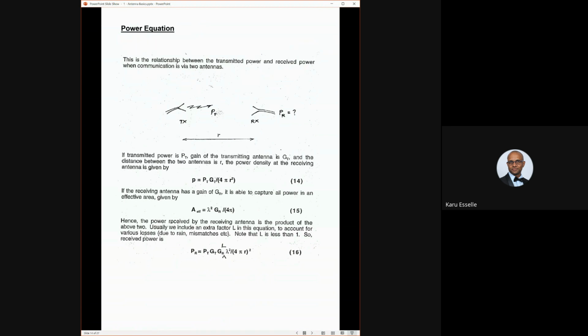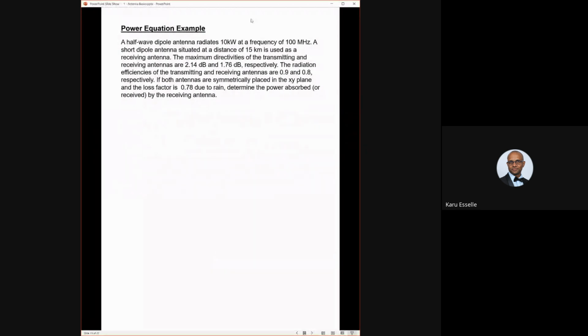But there's a decibel equation. You can write the whole equation in decibels as well. Then multiplication becomes summation, because in dB, when you convert to log, multiplication becomes summation. So there's a decibel version of the same equation, but if you're using this as is, you need to convert these gain values to linear values and substitute.